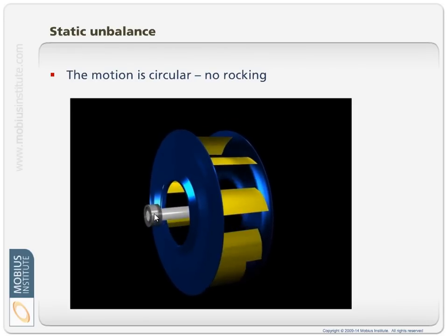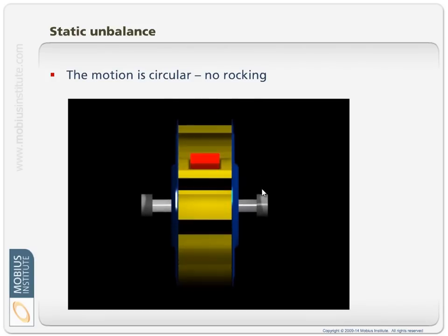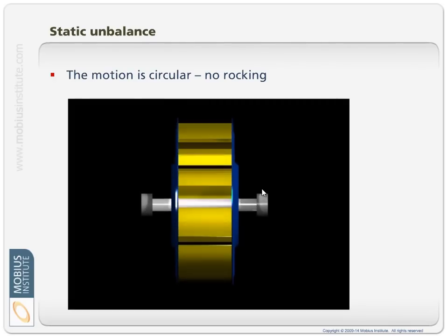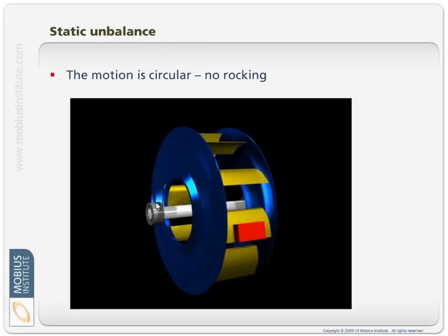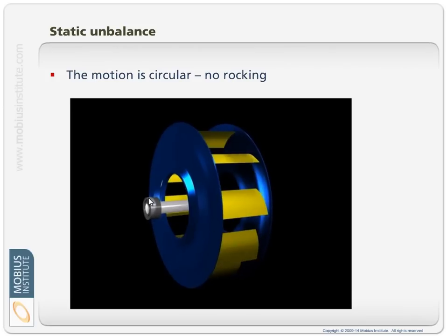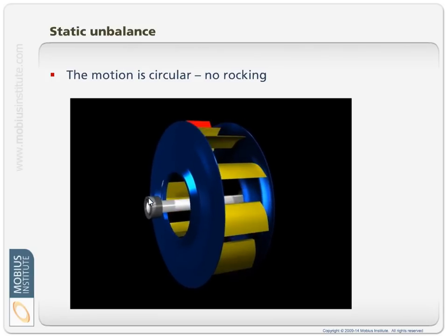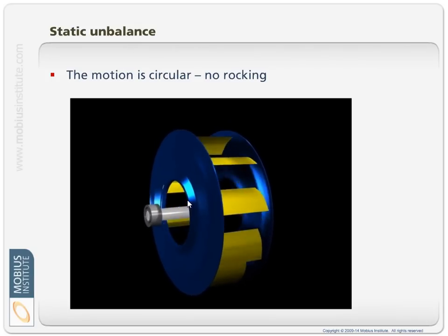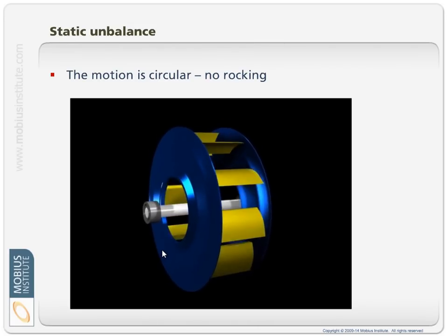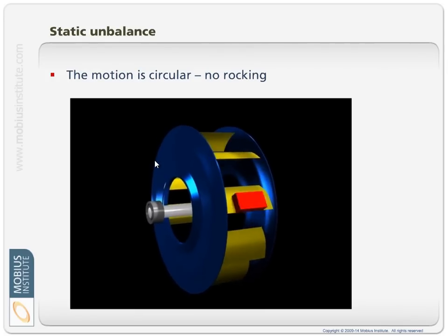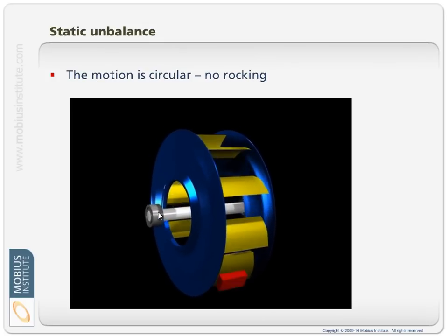So, that tells us a lot. From here, if we could take a phase reading, we measure vibration here, and we measure vibration here, and we see whether it's going up together, down together, up together, down together. If we compared the vibration vertically here to horizontal, we would see that they're both going up and down, but there's a quarter of a rotation delay between the two. So if you look at it, it comes out to the side, then up to the top, then out the other side, then down the bottom, then this side, up the top, and so on. There's a phase timing relation. If we could compare the vibration vertically to the vibration horizontally, we would see 90 degrees phase change.